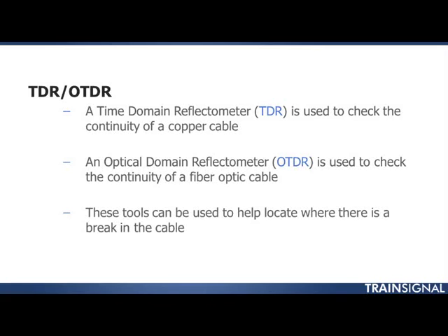So using a tool like this, we were able to find out that it was able to say, okay, your issue seems to be approximately, and I don't remember the exact numbers, so hypothetically we'll say it was 20 feet in from where this cable starts, right? We have this cable, we start from one point, boom, 20 feet out. That gave me the ability to know which desk to pull out away from the wall and look at that cable and see what's going on.